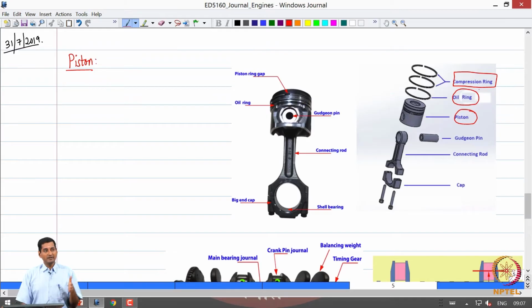In a matter of 1 second, the piston may undergo strokes in the order of 10 power 2, or 100 strokes. That's a lot of strokes in a very small interval of time. We need to ensure that we lubricate the surface of contact between the piston and the cylinder, so that we reduce the frictional effects which oppose the motion and reduce the energy loss due to friction.